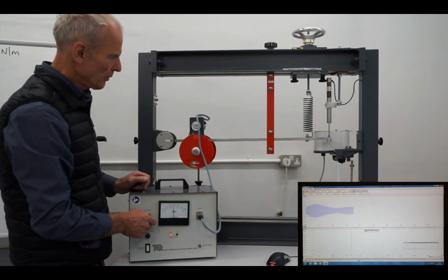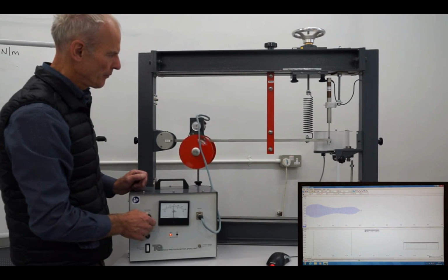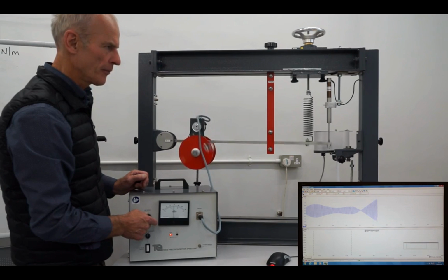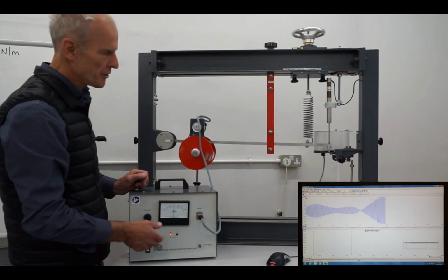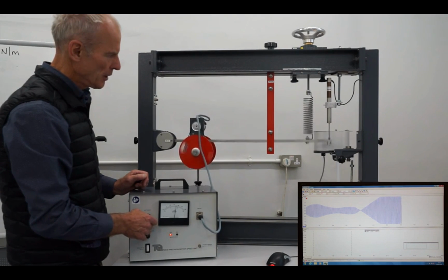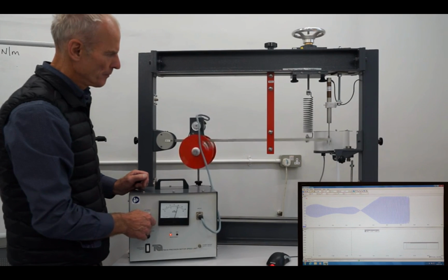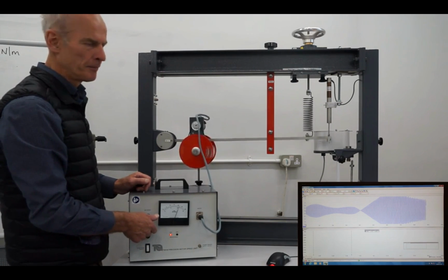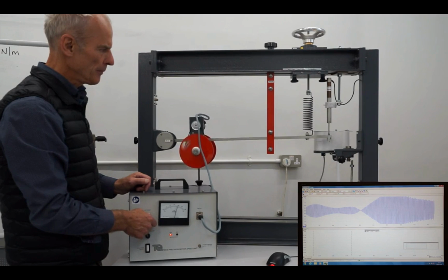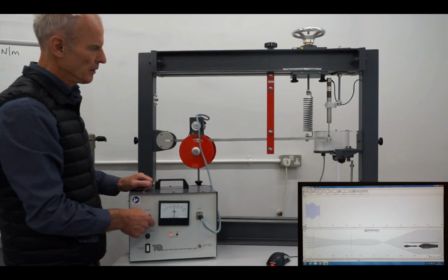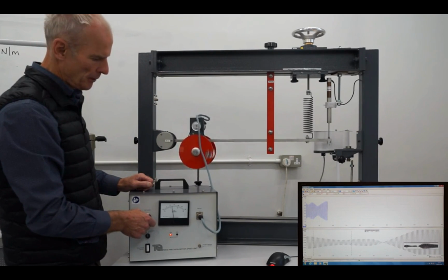So you can see here we're getting quite close to a larger vibration. And you can see this is approaching a damaging situation, like where something is into resonance. There's a knock in the sides. So obviously it's something you want to avoid. So we go beyond that. Calm it down. And that's taken that away. Or we can come back again, and come through here, and if we sweep through quickly, then there's a delay because of the momentum in the system, and we can avoid it and come right back down.